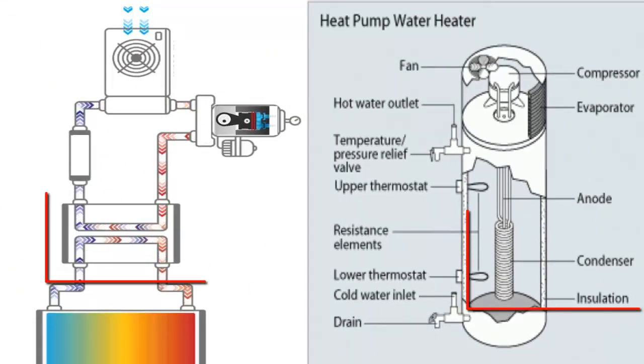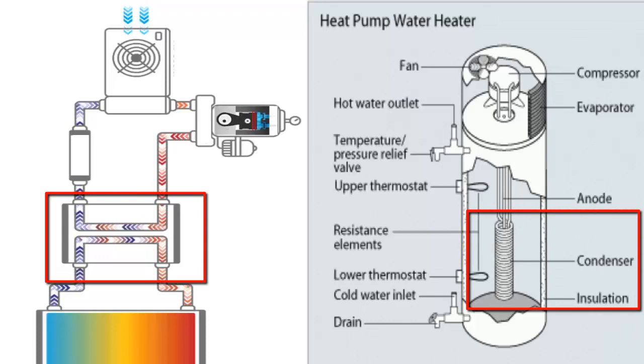B. Condenser is a heat exchanger always located at the outlet of the compressor, through which the refrigerant fluid in vapor form gives energy to the water in the tank, because it is thermally hotter than the water. As it releases energy, it condenses the refrigerant back into a liquid state, while the water heats up with this heat.